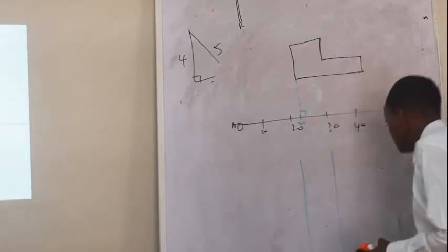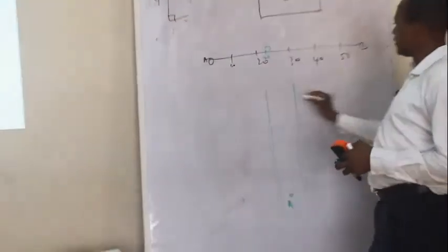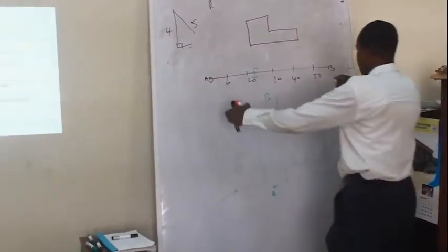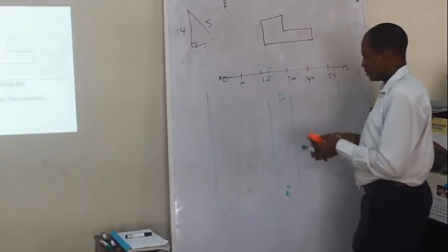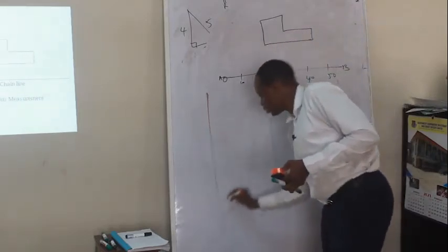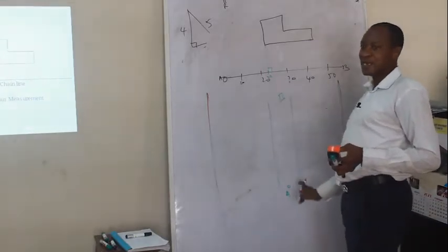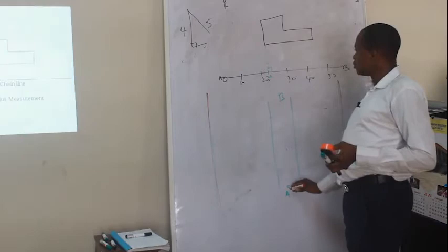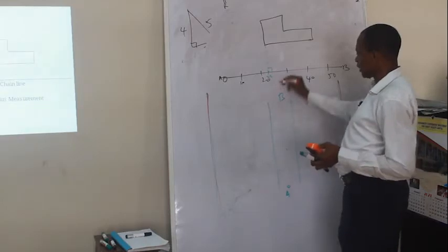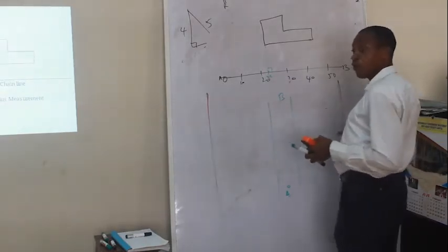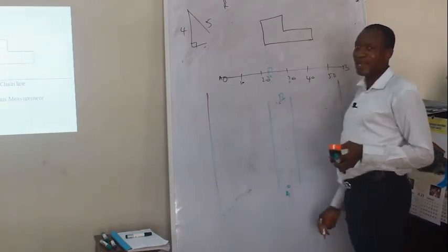The field book looks like this. It has a center. At the center, let's call this one A, and the other end there, B. This is the center of the book. This is your book. It has margins. At the center, you draw double lines. At A, it is 0. The end of this line signifies your line. This is on your page or your field book now. At B, let's call this one 52. That's the total length of that line.